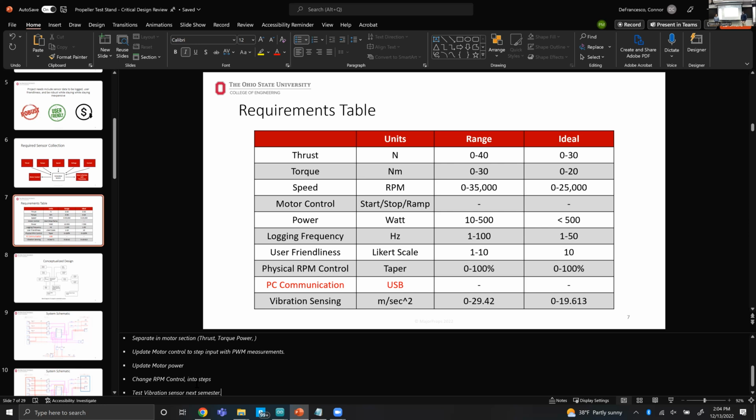Do you guys have previous PCB design experience? One of the members had it. But you can get to this if you follow the module and utilize the TA's expertise. That's why I was a little shocked at the price, but you can also ask the manufacturer, JLCPCB, to do the soldering for you if you don't have experience with very small components. They use expensive pick and place machines. It's more expensive, but you know that it works.